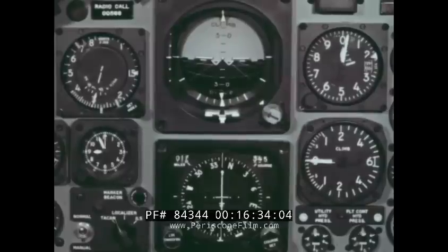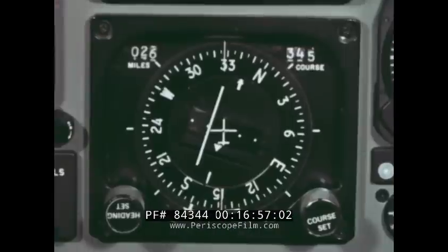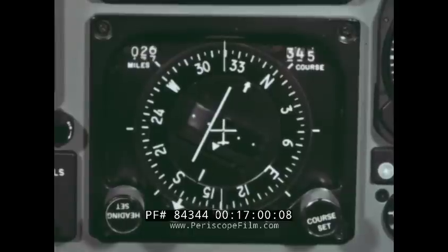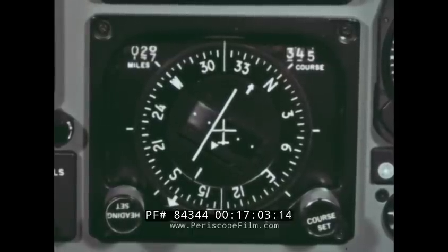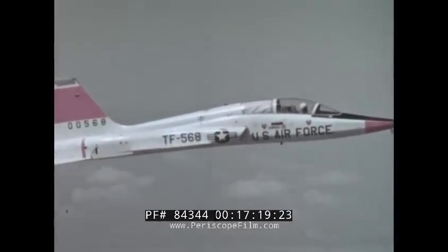Maintain the course until you see the need for a correction. Initiate a correction anytime displacement of the CDI indicates the need for it. Normally, a correction of between 20 and 45 degrees will be sufficient to put you back on course. In this case, you are using a 30-degree interception angle. When you reach your course, roll out with sufficient drift correction to maintain course. Now you're on the last leg of the flight, on course to Randolph-Tacan.